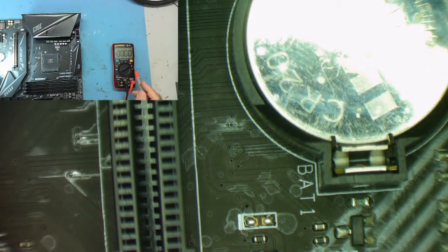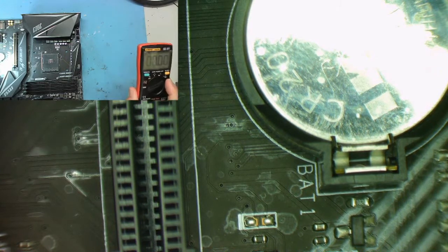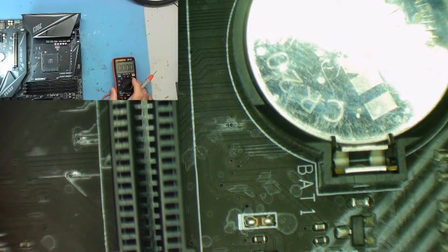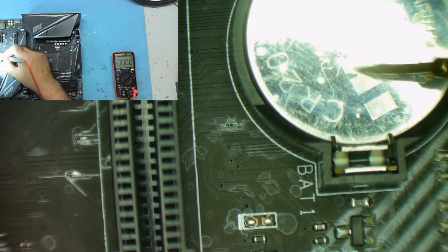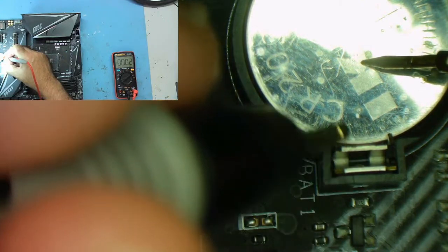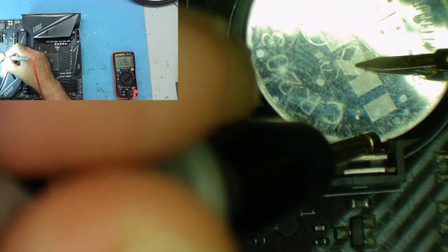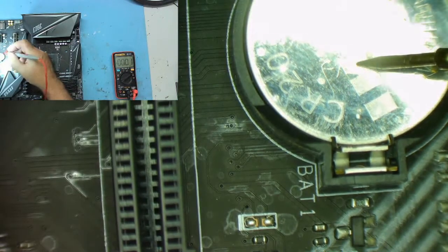Okay. Microamps. I use this one because it's a bit more sensitive than the Fluke on the microamps range. It gives you an extra decimal point. I'm expecting about 10, but it could be 1 or 2 microamps. So, positive probe on the battery, negative one to the little terminal, and then push the terminal back so you break the connection, and the current's then flowing through your multimeter. Let's see what we get. 2.6. Yeah, that's well within normal.